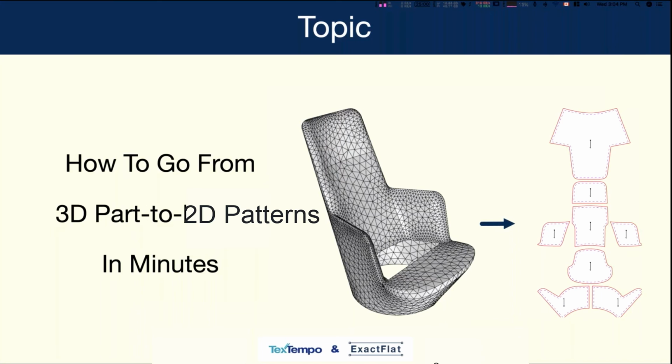We do have additional metrics that you can engage that will further minimize and reduce that error. However, it does so at the expense of increased strain on your pattern piece. So it will add more strain to the pattern piece to ensure that your perimeter lengths are the same. If you're working with a material like sheet steel that's going to be welded together, and you need to be absolutely certain that the two edges being welded together are the exact same length, you can use the no seam stretch feature of ExactFlat to help guarantee that your edges are going to be exactly the same length.